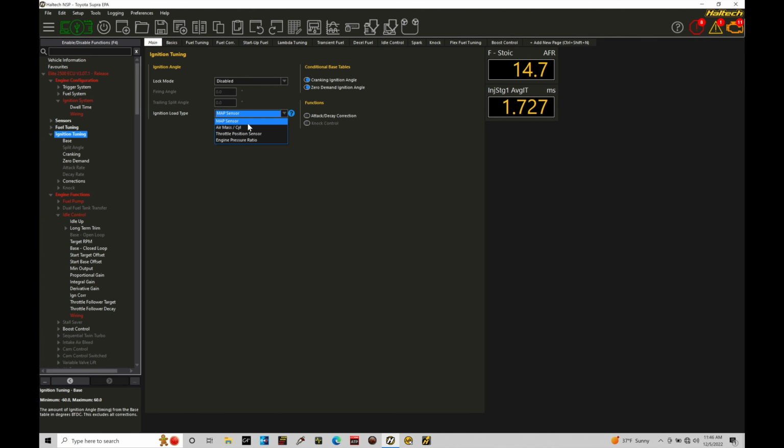I find it just easier to track things, easier to go about that, but air mass per cylinder is an option. Engine pressure ratio is, in my opinion, pretty irrelevant for dialing in spark timing. So MAP sensor is what I'm going to choose here, and that's what I'm going to go through in the tutorial here, assuming you're running MAP pressure, because that's going to apply to...